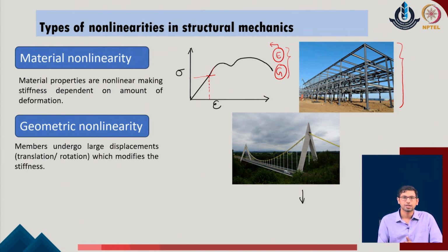But the understanding is that as the stiffness value gets modified due to the large deformations in the given problem, this also introduces a nonlinearity, which means that as the deformations increase, the system will experience a change in the stiffness. This could be an increase or decrease in the stiffness, typically known as the stiffening or the softening of the given system. But the understanding is that with the increased level of displacements, the system starts to have modified stiffness values, and we consider this particular aspect to be the geometrical nonlinearity of the given system.